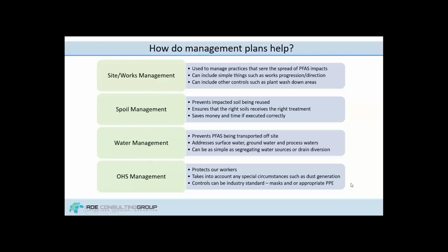site, such as dust generation, really high levels of PFAS, like we see in some firefighting training areas. And controls can be industry standard. The things that we can implement here to protect workers don't have to be terribly complicated. P2 dust masks or equivalent to prevent inhalation, and good hygiene practices such as washing hands after dealing with PFAS impacted materials.